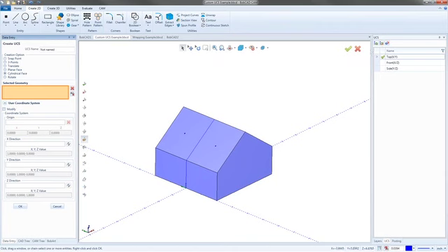So now what we'll see is the UCS opens up over here on the data entry tab, or wherever your data entry tab is. And the first thing we're going to look at is the creation option of a snap point. Now a snap point lets you pick a point that it's going to snap to. The problem is with a snap point, when you're trying to make a plane, a lot of times I want to make a plane that's not just a normal standard, flat plane in either the top plane, front plane, or side. But with the snap point, what it allows you to do is basically move your plane up and down depending on what snap point you choose, but also what plane you are using before you click the snap point.